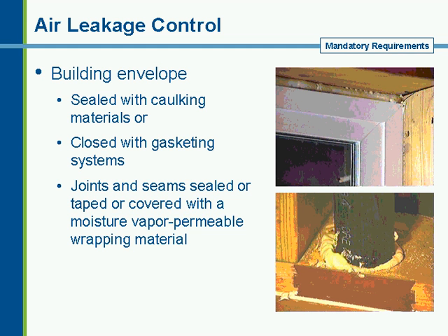Air leakage is pretty straightforward. Basically, anywhere there is a place that you can seal it, you must seal it. So around your windows and doors, make sure that they are sealed with a type of gasketing material, or if you're using sealing methods between dissimilar materials, you need to allow for the differential expansion and contraction of that material. So around all your plumbing is another area.